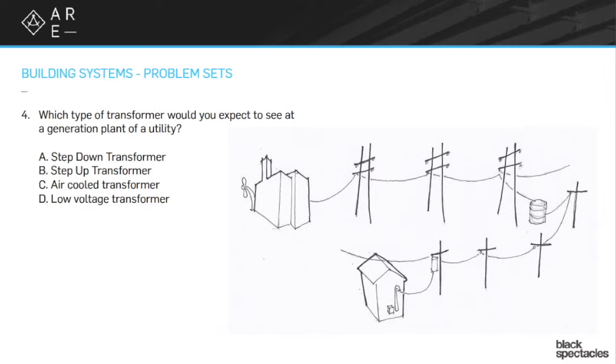If I have much lower voltages and therefore higher amps, the cross-sectional area of the wire goes up, is much larger. So you can imagine from a cost standpoint, if this thing is, say, 100 miles from the big city, and I would need to make the wires 5-6 times the cross-sectional area by keeping it at a low voltage, I'm just not going to do that if I'm a power company.